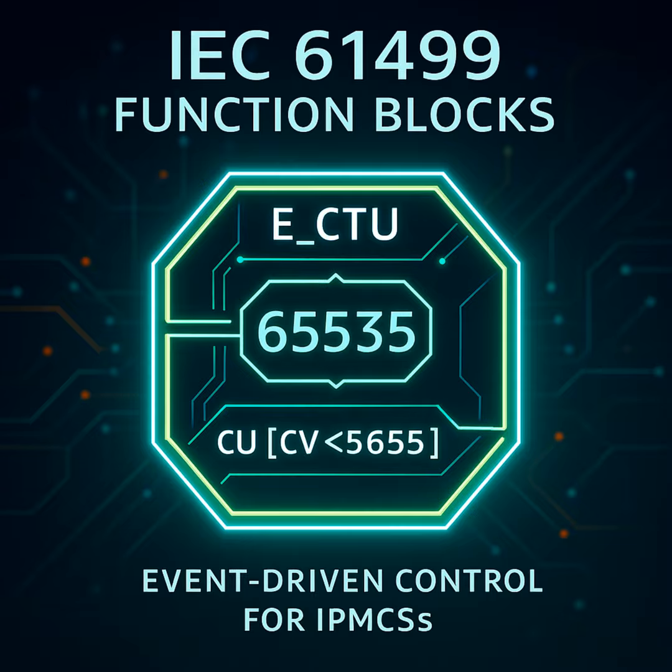Both PV and CV are defined in the standard as UINT. UINT, unsigned integer. So for everyone listening, that means 0 or positive whole numbers, right, up to a certain limit. What is it for a standard UINT, typically 16-bit? Usually, yes. 0 up to 65535. And that data type, that specific UINT constraint, is actually incredibly important. It's key to understanding why this block is so robust. Okay, holding that thought. UINT limit is important.